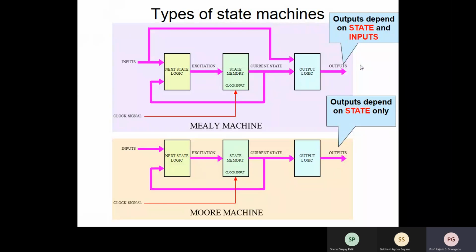Yes, sir. Whereas in a Moore machine, it is guaranteed that there won't be any asynchronous events at all. Everything happens on the clock. The same clock will be fed to the cascaded circuit, and so you will never have the problem of metastability there. But what is lost if you make it metastability proof using a Moore machine? The immediate response to a changing input will be lost. The output will be generated, but only at the appearance of the clock signal.